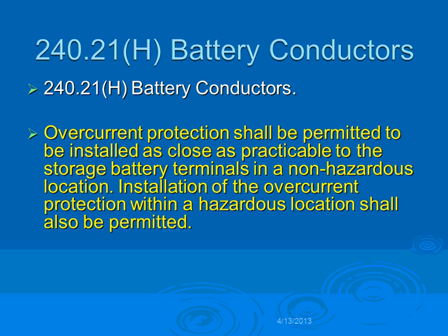Conductor-wise, the same thing, guys. Make sure your conductor is 1.25, go to next standard. You only start watching what you're doing when you hit the 800 amp. You have a panel at 800 amp, your conductors can be lower amp-wise, slightly lower. More than 800 amp, match the conductor to the overcurrent device on panels.